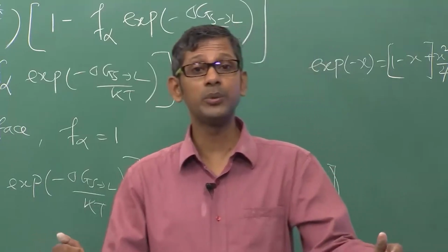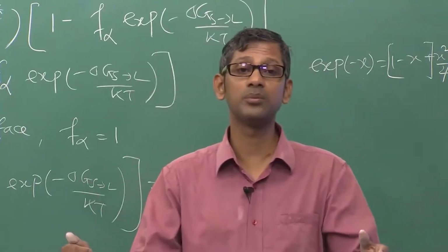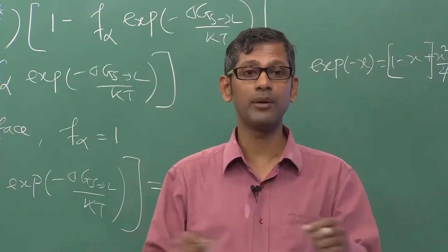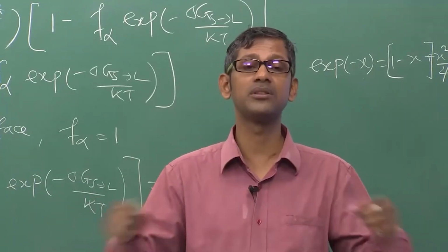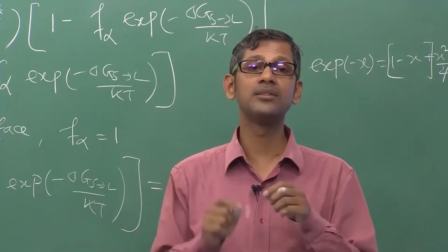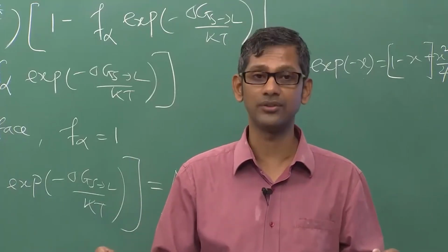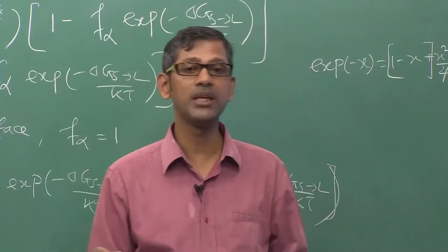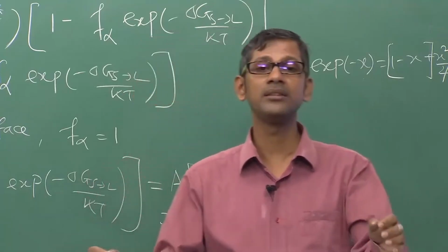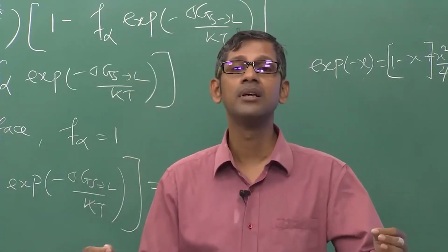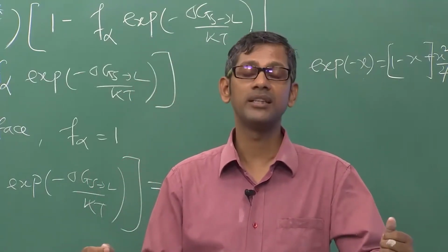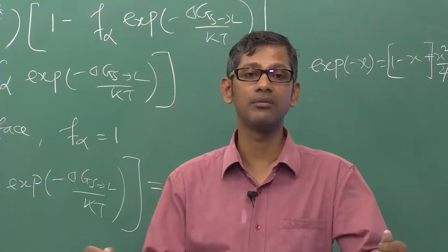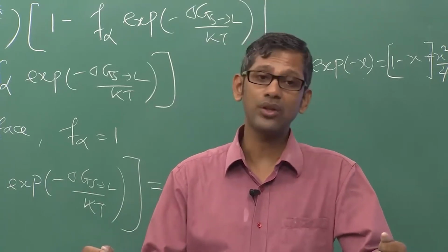You can also have a twin situation. In the case of silicon, that actually happens, you can have twin re-entrant angles. You can have surface twins present on the surface, and these twins can allow the atoms to get attached. And that is what happens in silicon more. That's why in aluminum silicon alloys, the silicon gets multiple twins, and they have all kinds of features built in on these silicon fibers. So that's also another possibility.